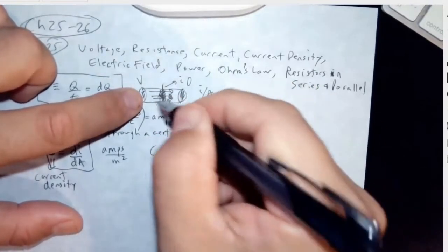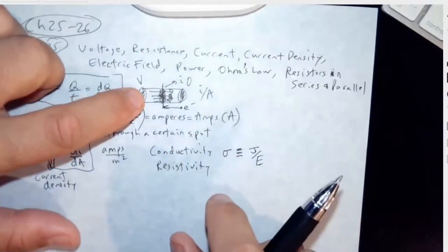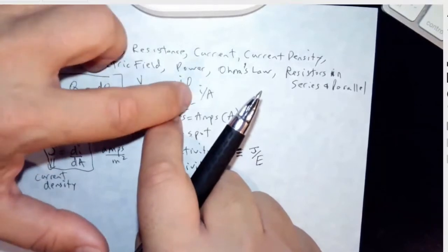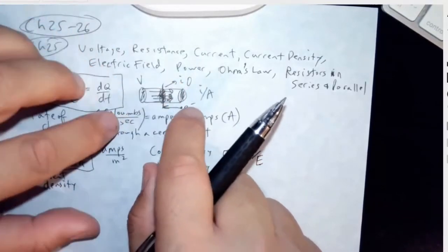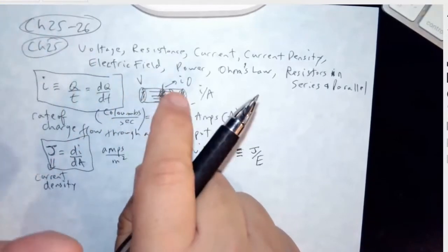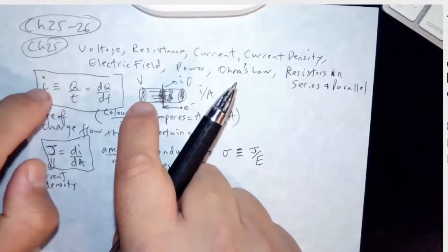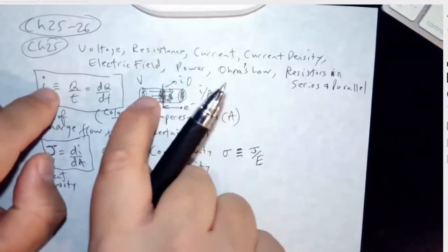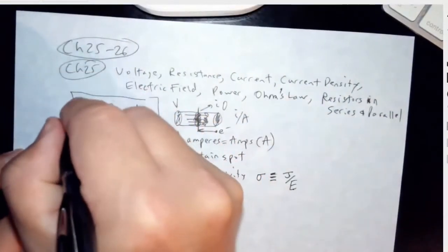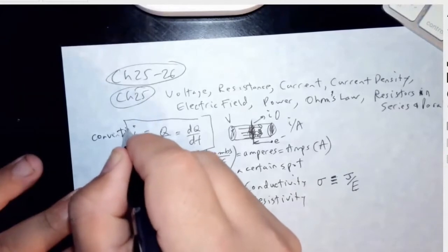It's actually negative charges that are flowing the other way, right? But that has the same effect. Essentially, positive flowing this way has the same effect as negative flowing the other way. So that's why it doesn't really matter. So that's why we can focus on conventional positive charge flow as being this way, from higher voltage to lower voltage. So this is conventional current,